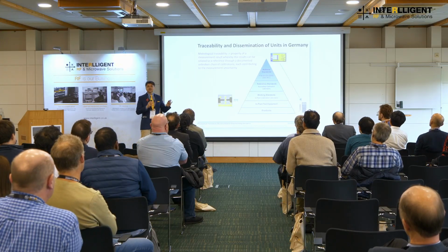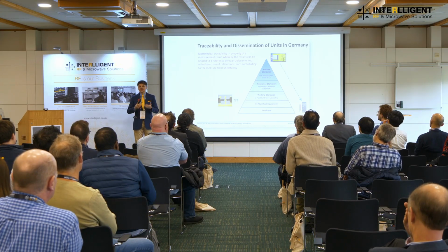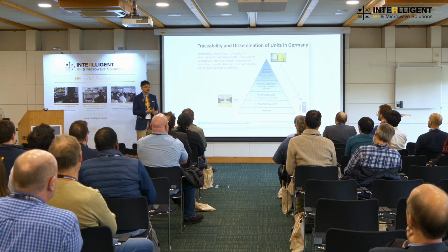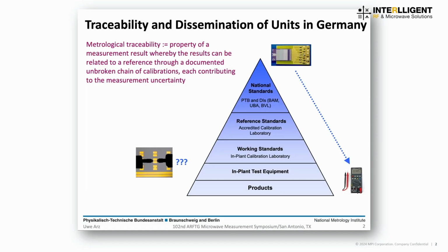First of all, let us talk a little bit about what traceability is and why it is so important for our measurements. In simple words, traceability is an unbreakable chain of mathematical computations which helps you to link a value you measure, a quantity you measure, with the physical constants that we know. And this chain is usually established at the national measurement laboratories like NPL here in the UK, NIST in America, PTB in Germany.